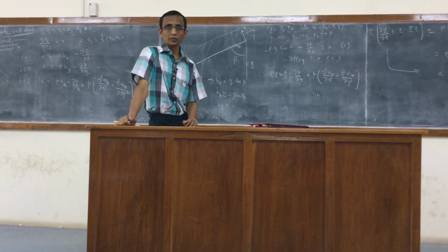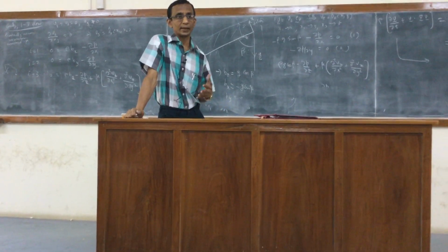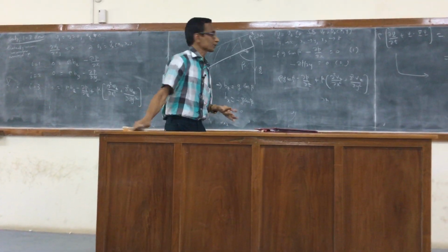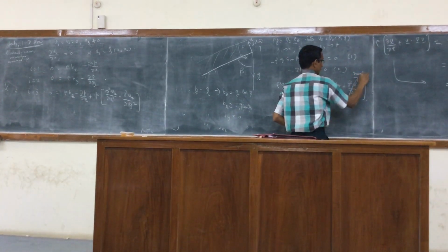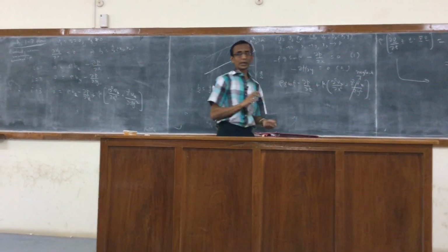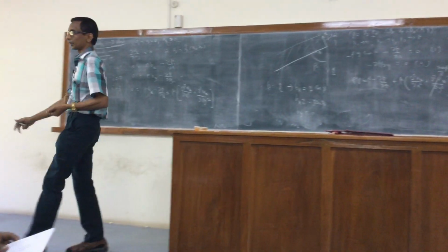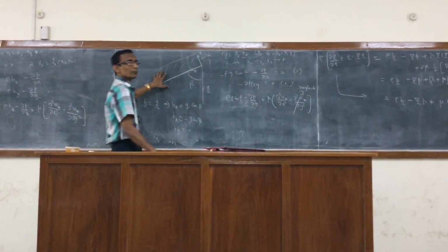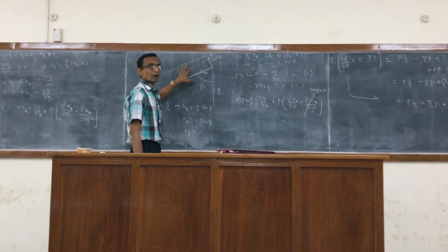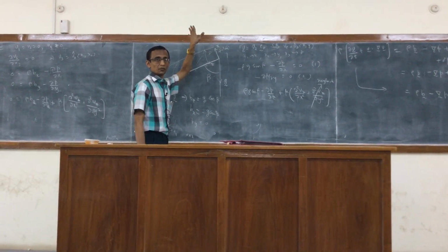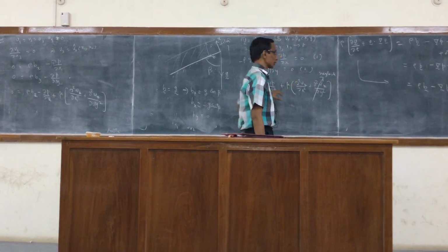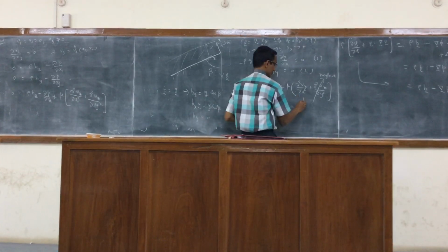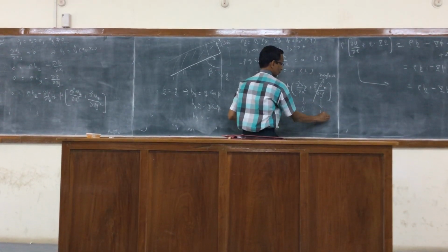Typically what is also done further: this is all the equations say, but now a further assumption is made to neglect this term in comparison with the other, based on dimensional analysis and on the fact that the thickness of the film is much smaller than the width of the film. The characteristic length along the x direction is delta, and that along the y direction is w.